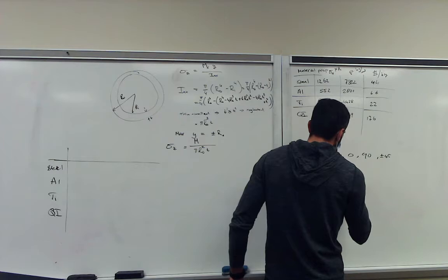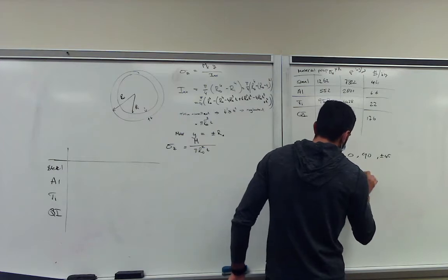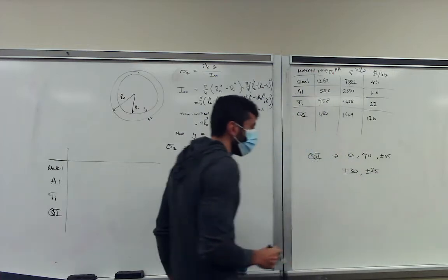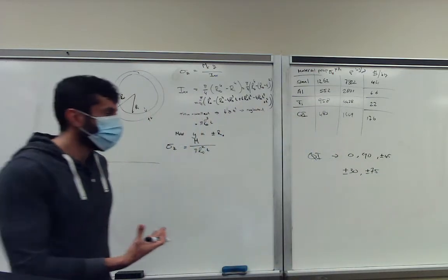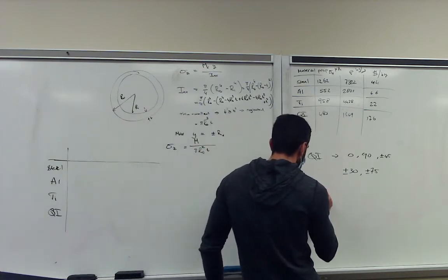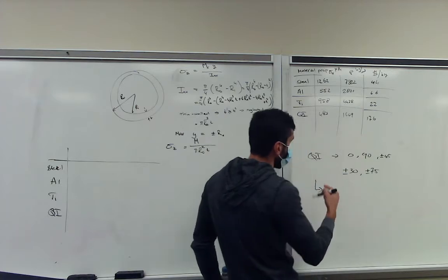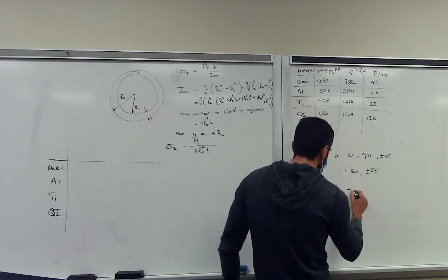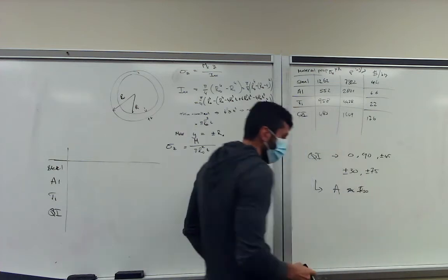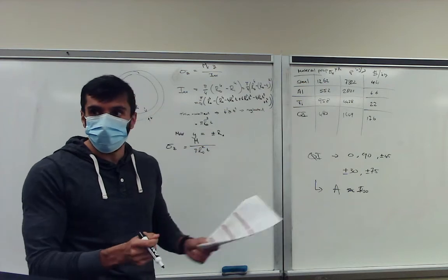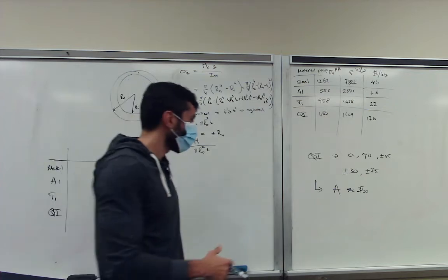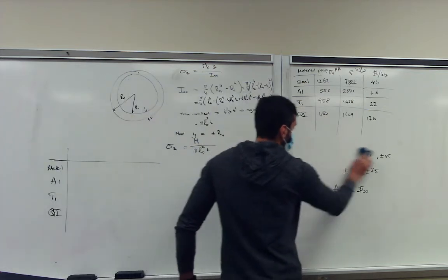But similarly, you can also make it out of plus minus 30 degrees, plus minus 75 degrees. That will also be quasi-isotropic. It has to do with the fact that if you determine it for a composite, we can sidetrack a bit, the extensional matrix, the A matrix, becomes equivalent to an isotropic one. So if you would basically pull on that laminate, it would have equal stiffness in the 1-2 direction. So that's the term quasi-isotropic.